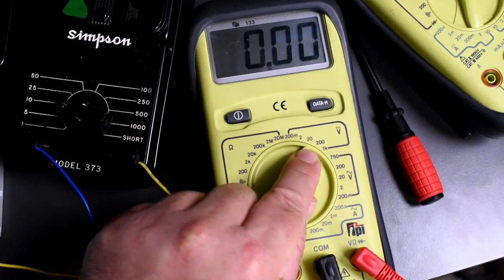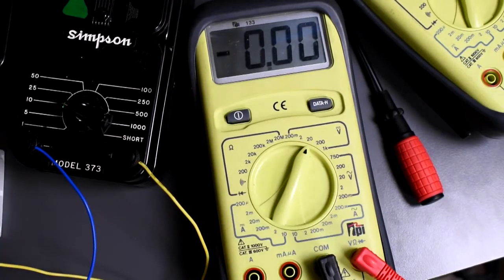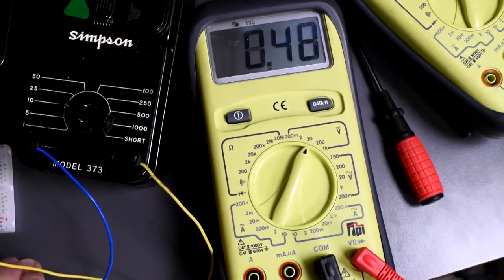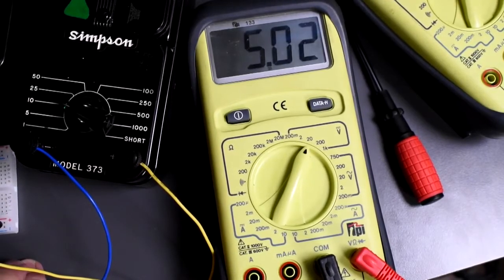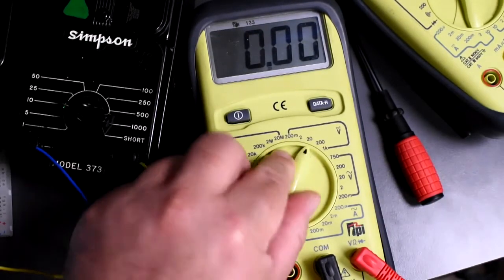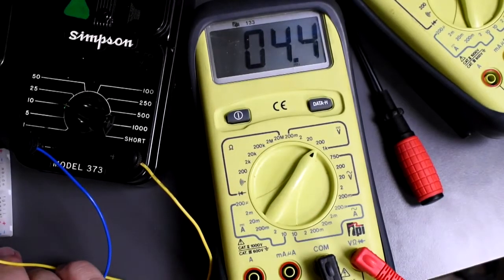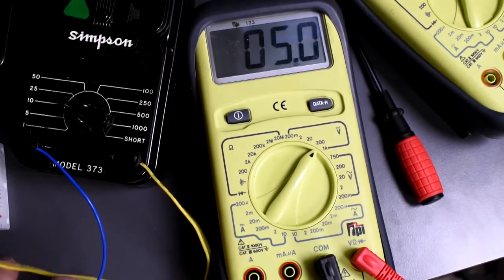So this is 20 volts. Can we measure 5 volts with 20 volts? Yes. So let's see here. I'm going to put the leads across the power supply, and this meter shows 5.02 volts. Okay. Now, can we measure the voltage with the 200 volt range? Yes, we can, but we are not going to get as accurate a reading as if we selected 20 volts. You see, this one shows 5.0. The decimal point has shifted. Okay. So this is 5.0 volts. It doesn't show the 5.02.